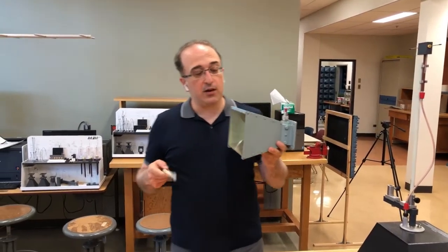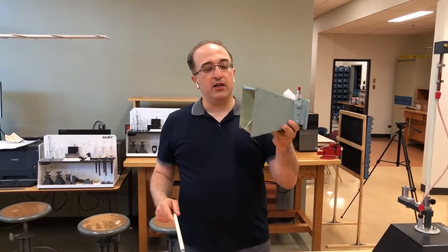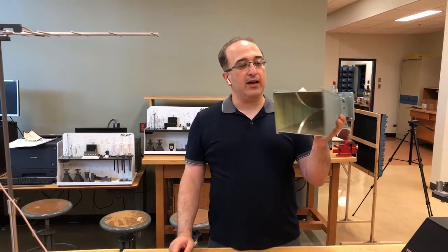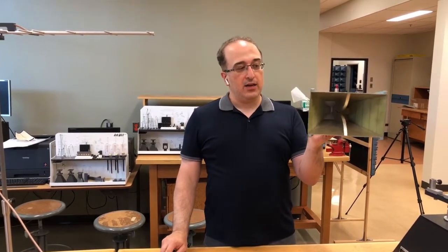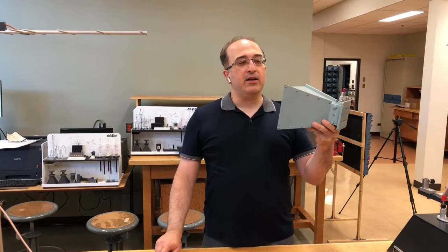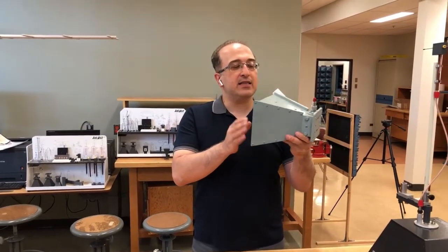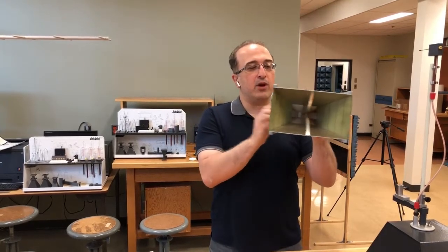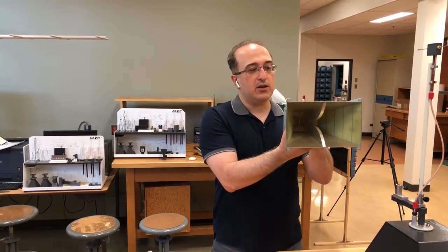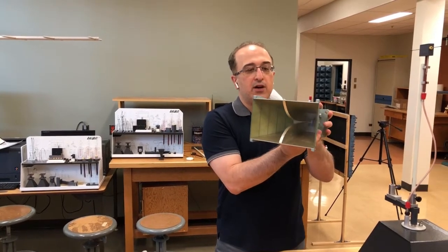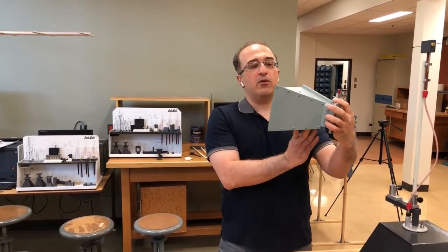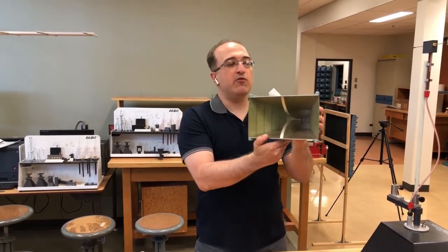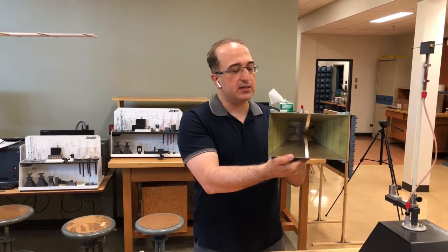What we're going to see in the compact range is that I'm first starting movement in the H-plane, so the antenna will move like that. And instead of going all the way 360 in the compact range, I'll go from minus 90 to 90. So assume that this is minus 90. It will start from here, minus 45, and then 0, and then come back again to plus 90. So that's our H-plane movement. We don't go to 360 for this demonstration.